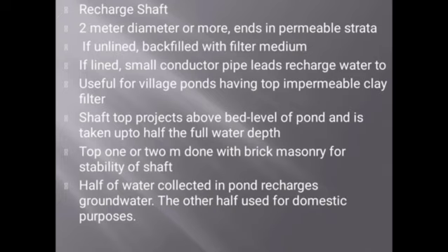Next method, recharge shaft, 2 meter diameter or more, ends in permeable strata. If unlined, it is backfilled with filter medium. If lined, a small conductor pipe leads recharge water to the shaft. Useful for village ponds having a top impermeable clay layer. The shaft top projects above the bed level of the pond and is taken up to half the full water depth. The top 1 to 2 meters is done with brick masonry for stability of the shaft. Half of the water collected in the pond recharges groundwater, the other half is used for domestic purposes.